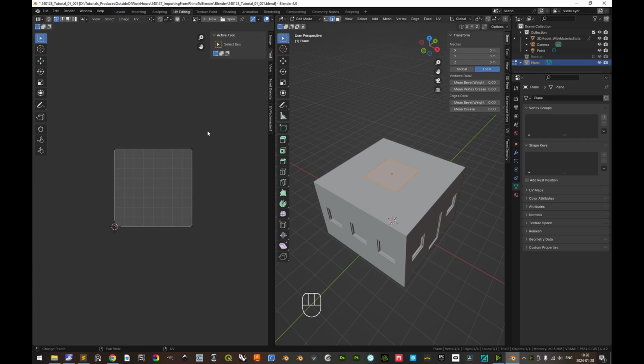And since we are already in the UV editing workspace, we can see here, since we had the generate UVs checked, we have this 2 × 2 meter plane as a UV island that goes from the UV 0 to 1, 0 to 1 UV space here. Now we want to create a new image, so we press the new image button there. The name can be templates.